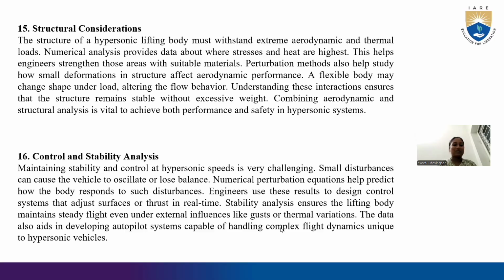Control and stability analysis. Maintaining stability and control at hypersonic speed is very challenging. Small disturbances can cause the vehicle to oscillate or lose balance. Numerical perturbation equations help predict how the body responds to such disturbances. Engineers use these results to design control systems that adjust surfaces or thrust in real time.